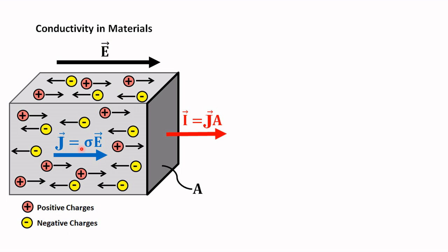So this depends mostly on the properties of the rock and also the type of salt that is added in this or the type of moisture that is present inside. So from this we can understand that electrical resistivity or electrical conductivity is a physical property of this material that is being used in the electrical method.